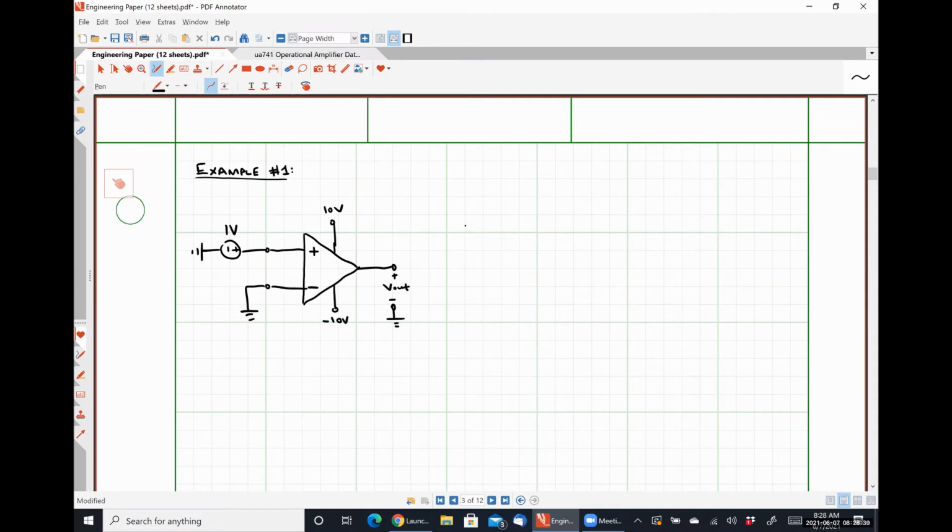I'm going to characterize this op-amp by its 3 parameters of importance. My open loop gain, AVOL, and we're going to say that it is 100,000 volts per volt, which if we looked at our uA741 op-amp datasheet would actually be low, or less than typical for that particular type of amplifier. So 100,000 for our gain is actually kind of low.